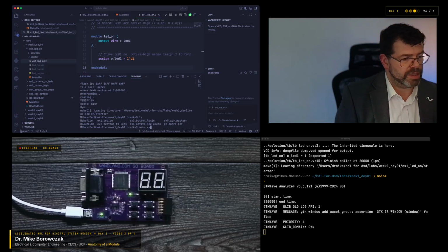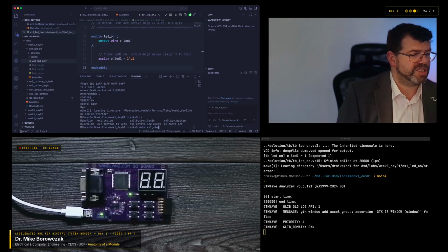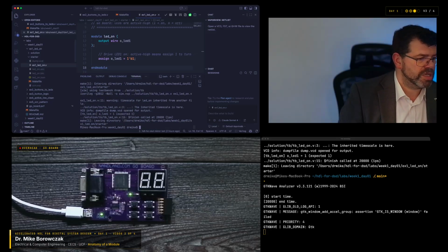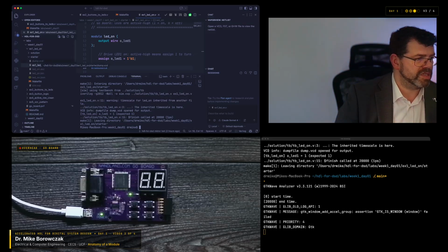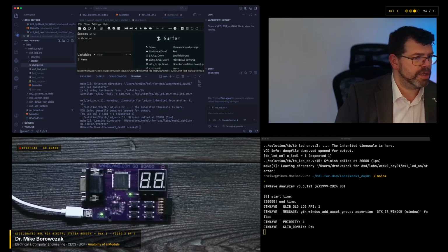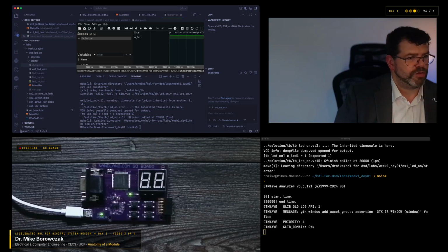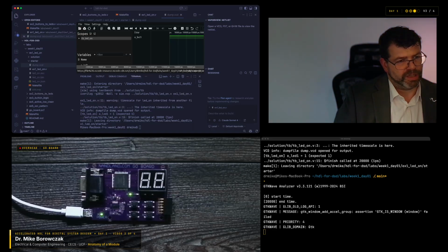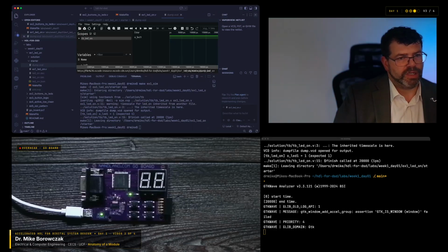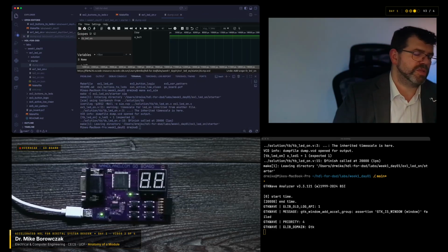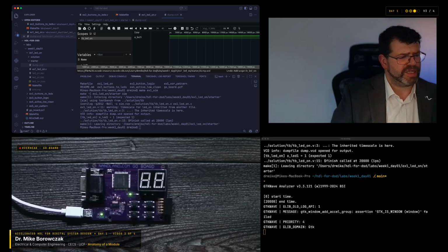Now there's some other fun things we could do. We could do make exe_1 underscore sim. See if there's any simulation. All right, well, what's really cool about that is there is a simulator. And if I open up now the dump VCD that was just created, I will now see a simulated version. Now this is pretty not fun in the sense that all we're doing is observing the output here, right? But this output here is always 1. And basically we're able to show that.